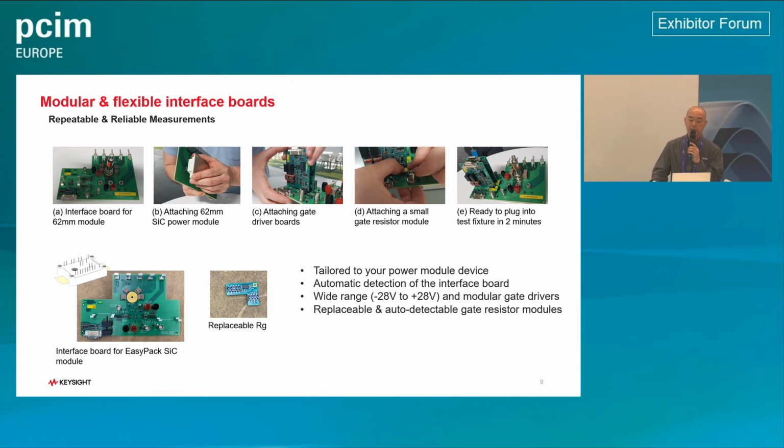So Keysight makes the tailored interface board for your power module. As you see on the upper side of the slide, it is solderless contact, so you don't have to use soldering to make a good contact. And also, the layout is optimized to make the parasitics minimum.